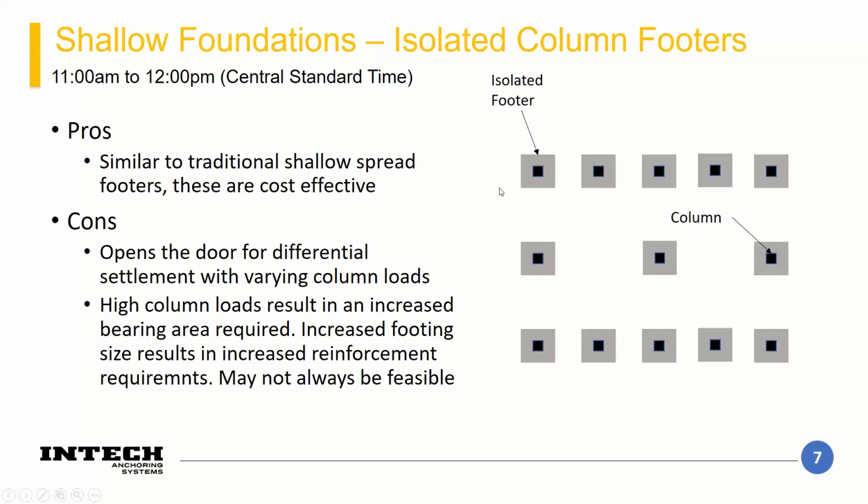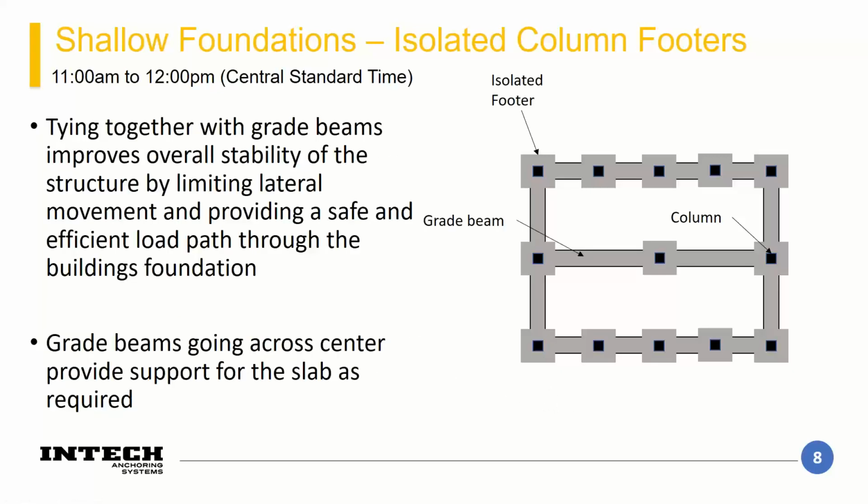And the other thing is, as these structures get larger and larger, your loads have to increase as a result. And with an increased load, you're putting an increased bearing stress on the soil. This may result in having to have a very, very large footing size, to the point where it's not really feasible to use this without considering some deep foundations or other foundation elements that you have to add.